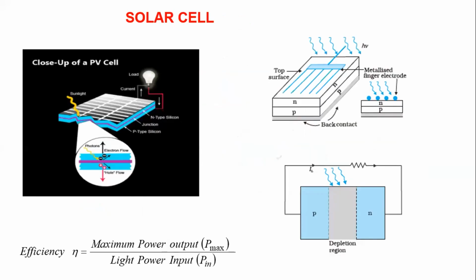And the solar cell, the same thing, whatever we see in the photodiode, the same thing in the solar cell. Slight difference, we won't apply any potential. Though it is reverse bias, we will give 0 volt. No reverse bias voltage will be given. So whatever the solar energy, typically in the case of silicon, most of the energy from the IR will be greater than the band gap, so it will be absorbed and we will get the current or voltage.